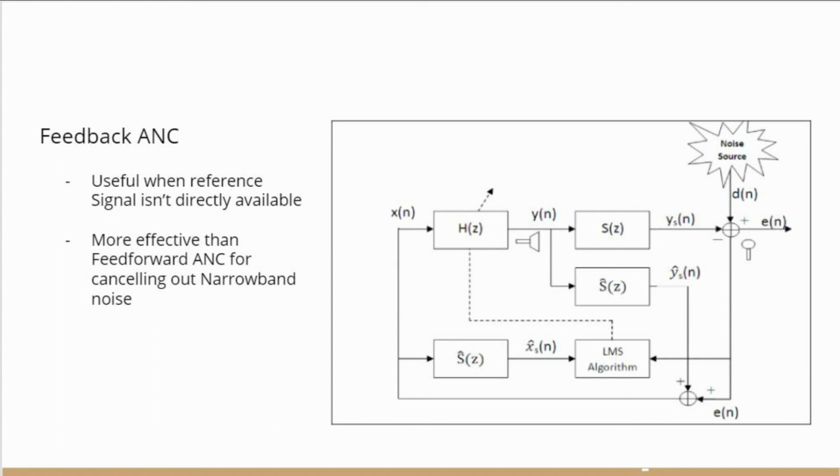It is also the signal along with E(n), which travels to the LMS algorithm that adjusts the H(z) accordingly. And then there are also hybrid ANCs which combine the two and other less common ANCs, but I do not have the time to talk about that here.